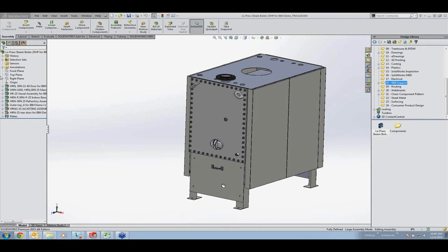To demonstrate when you might want to create those types of patterns, I have an assembly here prepared. If I drag my assembly, you'll see that the IGUS chain down here updates automatically. The other type of chain here is different in that the sketch is going to transform. So when I move this linear actuator, it does not automatically rebuild because the sketch needs to be rebuilt. So go ahead and do a rebuild, and you see that it will rebuild the IGUS chain, but the sketch geometry changes.